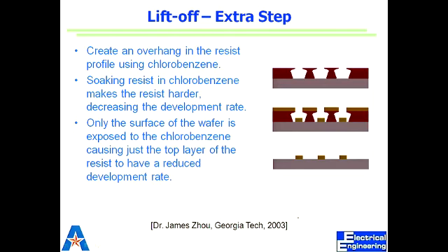Etching of gold should be easier than any other thing because it doesn't react, it shouldn't stick on. Yeah, that's another thing, how does it stick to silicon? We don't stick gold directly on silicon or silicon dioxide. We use a sticky layer, a very thin chrome or titanium layer, which sticks well on both sides, like bonding. So whatever method we use, mostly it's physical evaporation, or E-beam evaporation specifically. We always deposit a thin layer of titanium or chrome, and then we deposit metal.